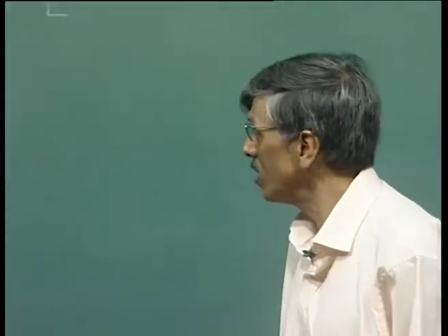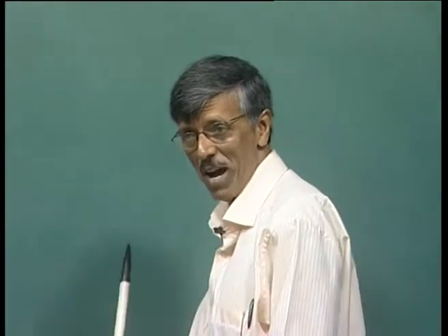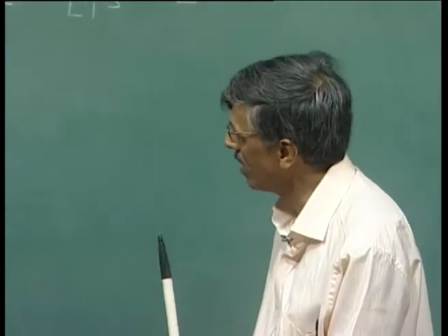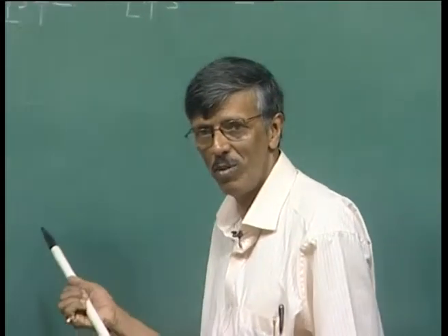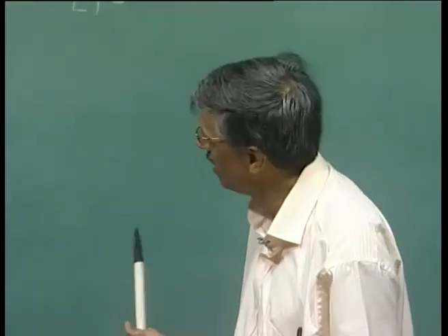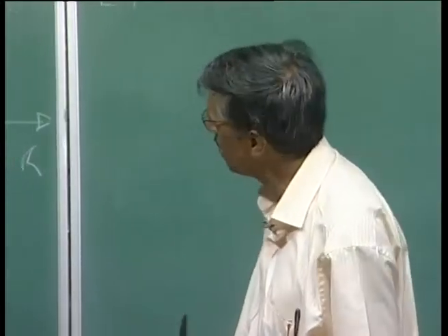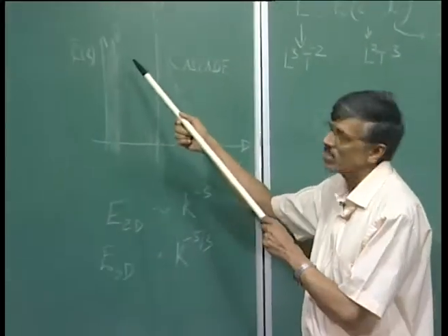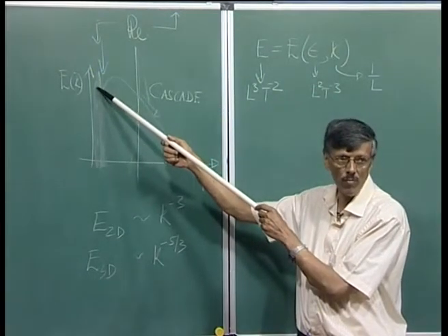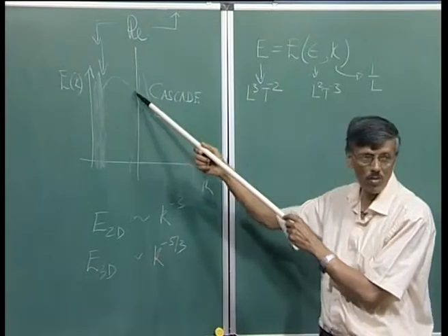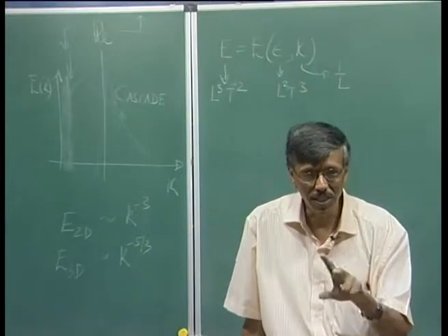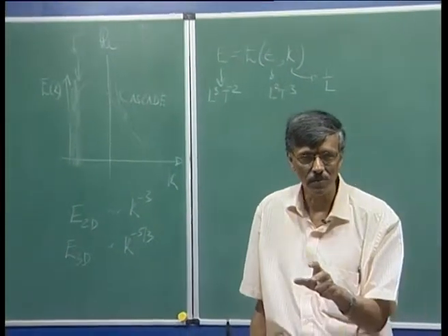Okay. So, now I think we have a fairly decent idea of what happens in a turbulent flow, which we got by very little investment. We have mostly depended upon dimensional analysis, and we have said something which is very true: if we have a statistical equilibrium steady state, then the energy that comes in here cannot reside there, because of the role of the nonlinearity versus the viscous term.